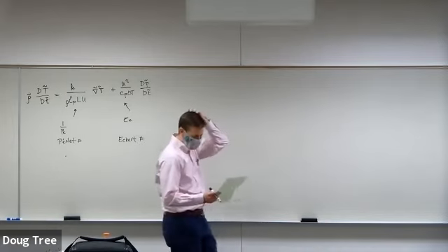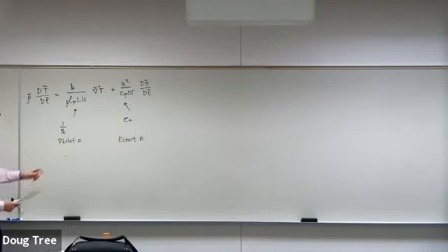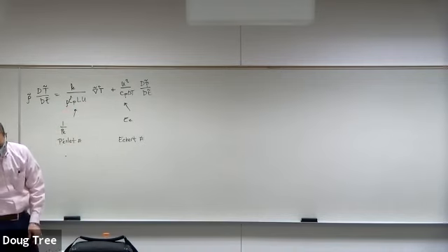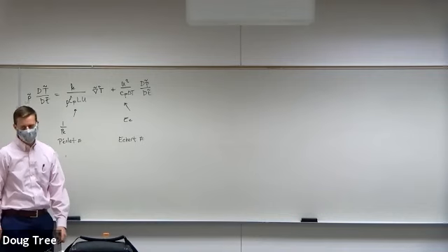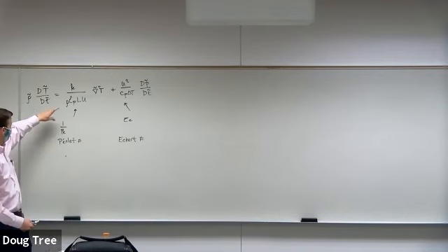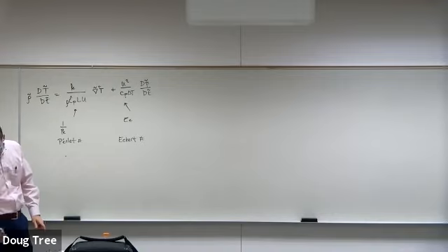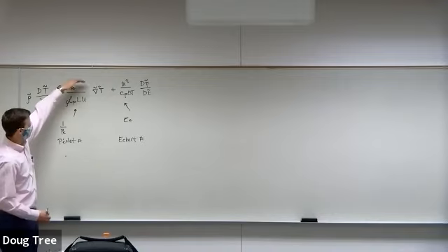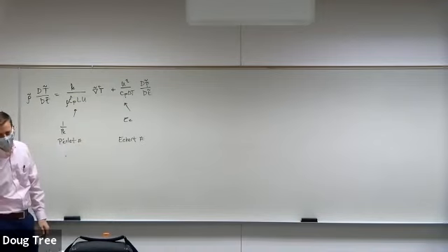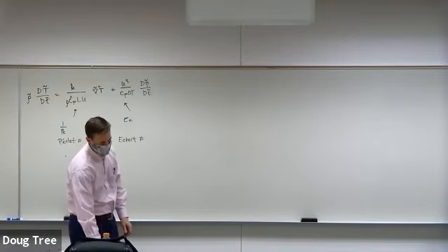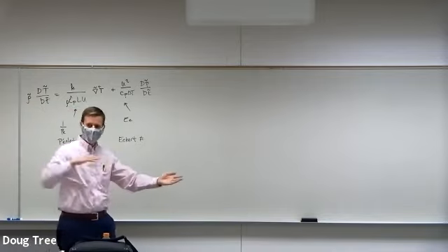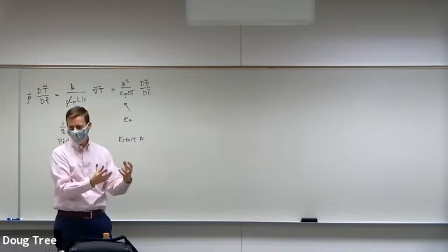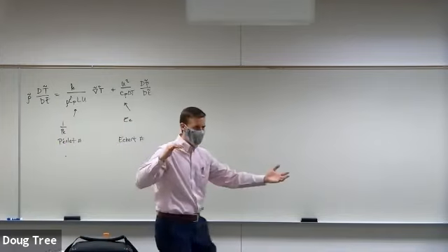Okay, so what's going on here? So this term is a ratio of the convection versus diffusion. Okay, so it's 1 over the Peclet number. So the Peclet number is convection over diffusion. So this is diffusion over convection, okay, here. But what that's telling you is, if the Peclet number is high, then my velocities are high. So think I've got lots of shear, and there's not much time for diffusion to happen, relative to the temperature that's getting pulled along.